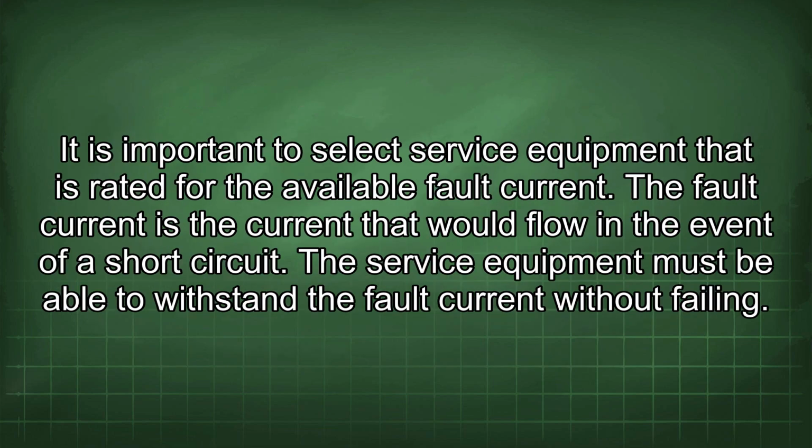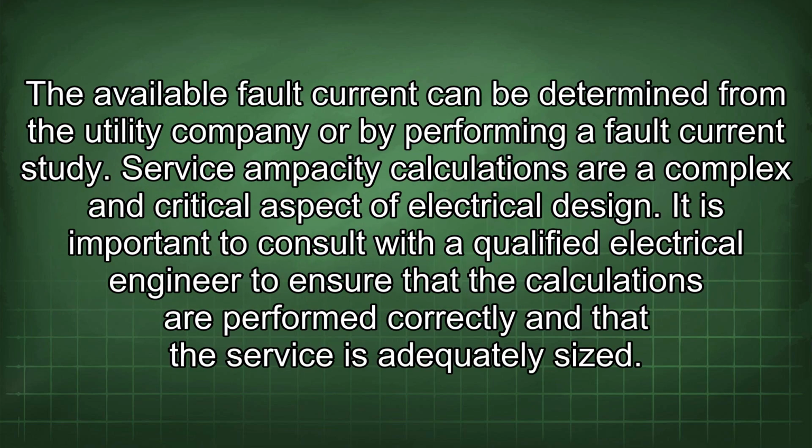It is important to select service equipment that is rated for the available fault current. The fault current is the current that would flow in the event of a short circuit. The service equipment must be able to withstand the fault current without failing. The available fault current can be determined from the utility company or by performing a fault current study.